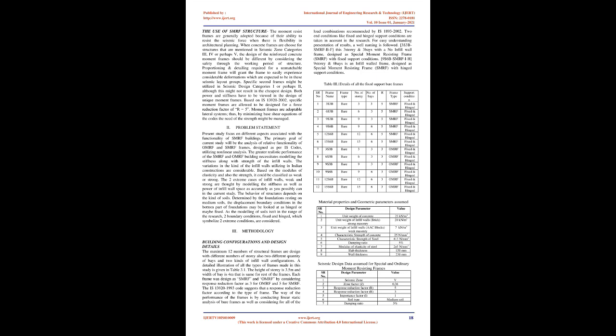The use of SMRF structures: moment resisting frames are generally adopted because of their ability to resist the seismic force when there is flexibility in architectural planning. When concrete frames are chosen for structures in seismic zones 3, 4, or V, the design of the reinforced concrete moment frames should differ, considering safety throughout the working period of the structure. Proportioning and detailing required for a special moment frame will allow the frame to experience considerable deformations which are expected in these seismic design groups.